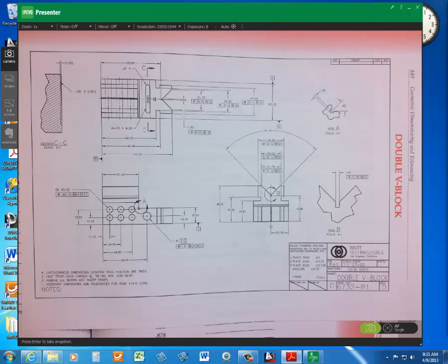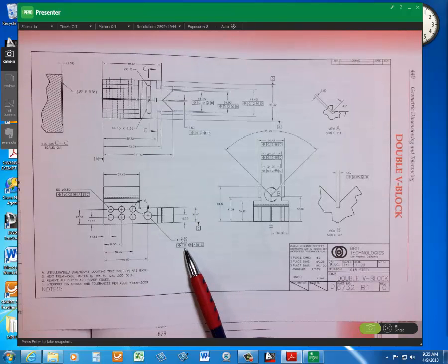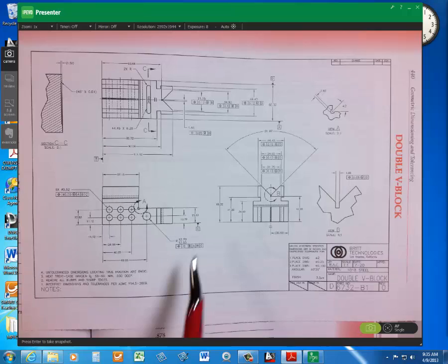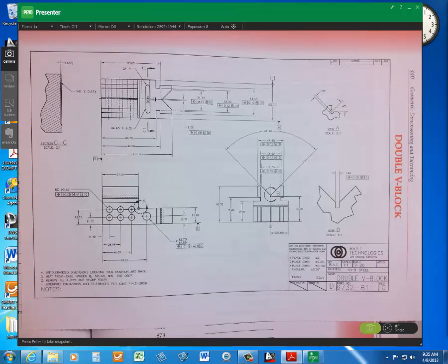How's it possible to have a 0 position tolerance? Because we put a 0 on it. All right, let's look at the 12, this one here. This is a technique. It's possible to do it because I can put a 0 on it. The 0 position tolerance just applies at the MMC size of the hole. So it basically says it's got to be right on. So there's no wiggle room in here.